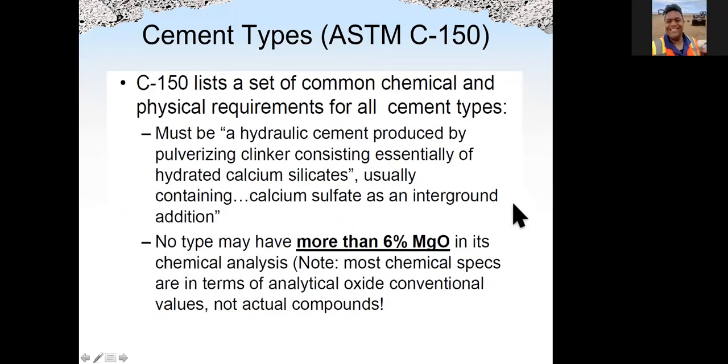Professor? Yes. I have a quick question. Sure. When you say sulfate attack, what do you mean? That is the sulfate coming from the groundwater or the soil. That will react with one of the hydration products in concrete, which we call monosulfoaluminate. You're going to see the chemical reaction in a moment. That will cause another new product we call ettringite. Ettringite will expand and cause concrete to crack. When concrete cracks, all kinds of problems will generate, so we do not want that. We will talk more about that. Good question, thank you.